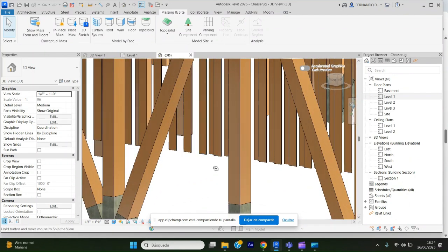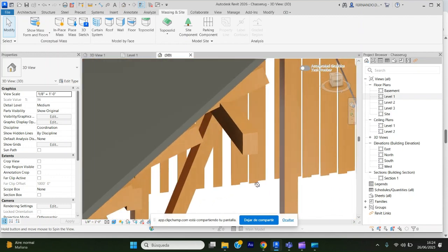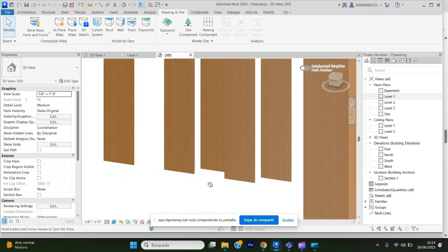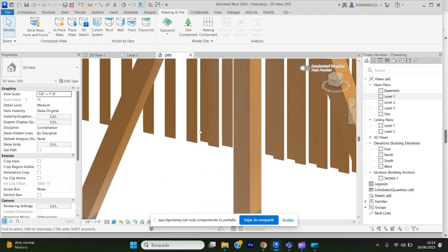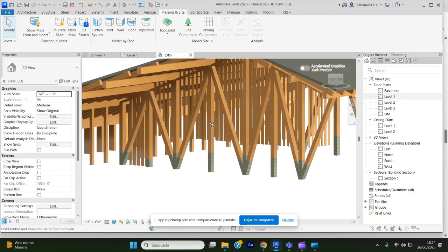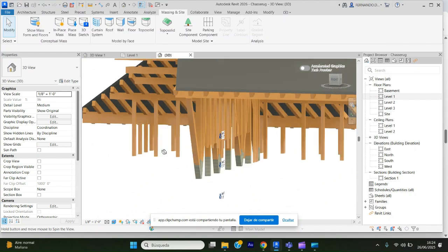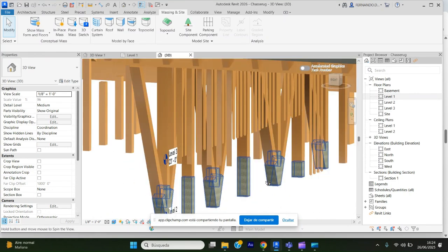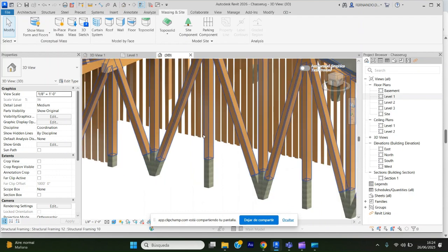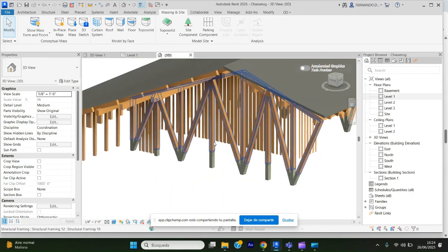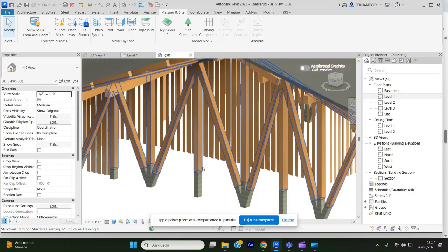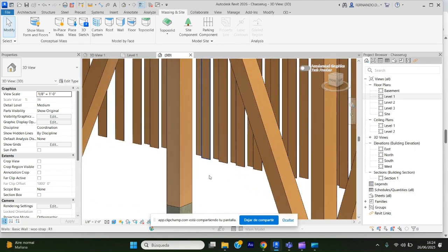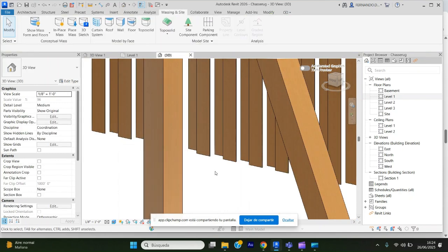Probably I haven't turned all the, yeah, but that's the effect that they have. Okay, so they have this so that it filters the light, but you are not exposed to the light, you are always in shade. And that would be enough because in Revit gravity doesn't exist, but of course in real life we have to do something here. So probably there will be a structural element nailed to these solid columns of the truss, and at the same time all those straps will be nailed to the solid element.